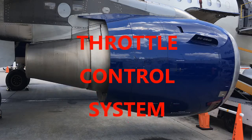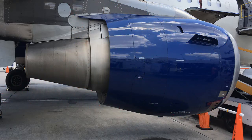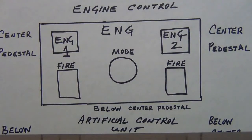The throttle control system that we have, like I said, is two thrust control levers, and when the aircraft is turned on, they don't automatically move. Because some aircraft have it so when you're in automatic, and by the way, there's automatic and manual start, in your automatic mode, those thrust levers do not move on their own. That's a test question, by the way. So just keep that in your notes.